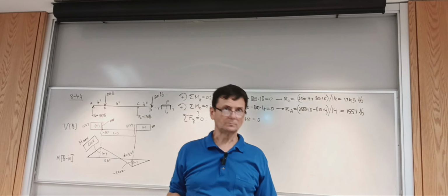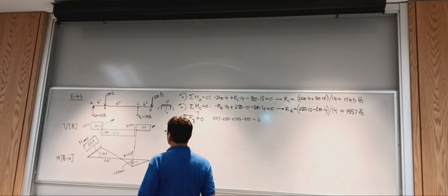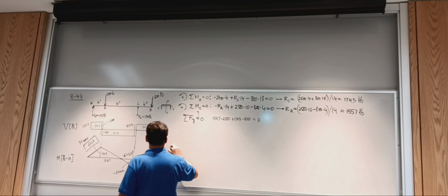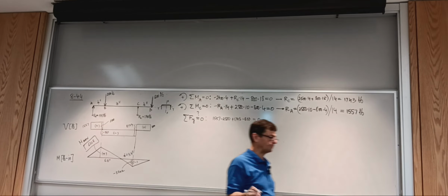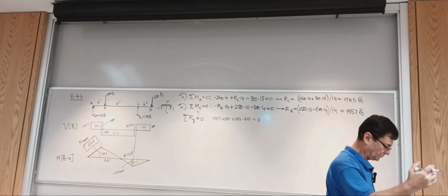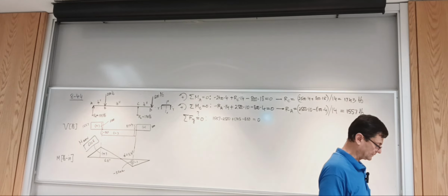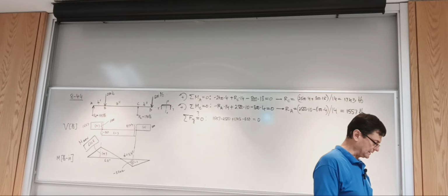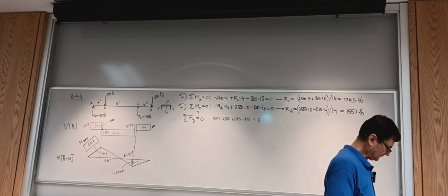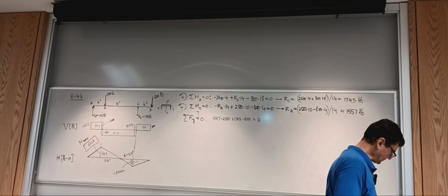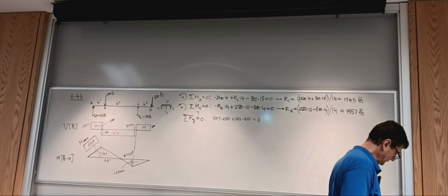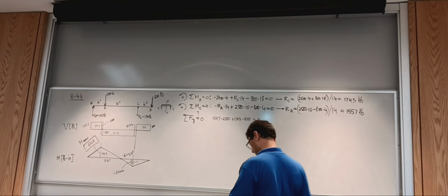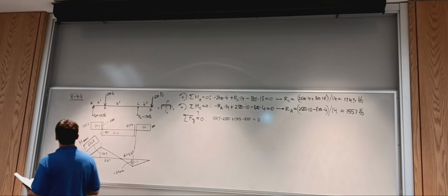Working with section modulus is convenient because you have one single value to match with what's available, or select from the table. So we know that the material for this channel is 6061 T6. And you go back to the problem. So the problem is 8844. Okay, so we have 6061 T6.